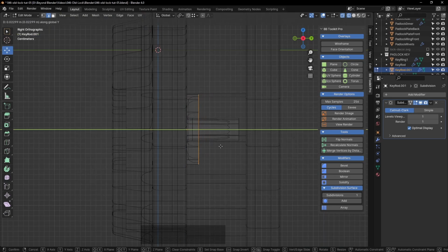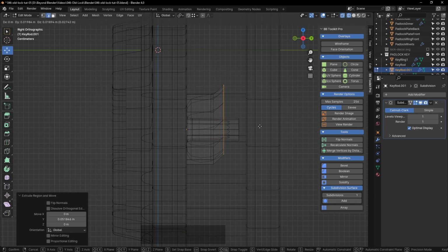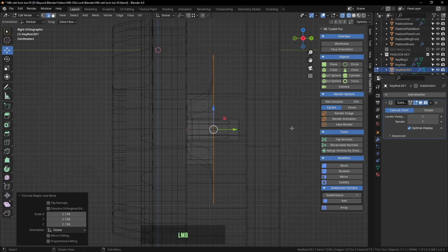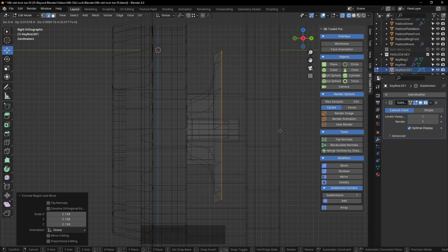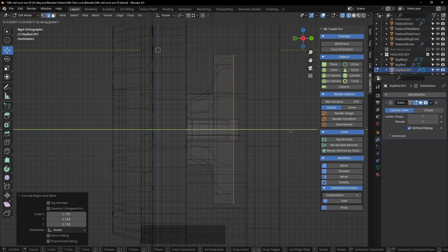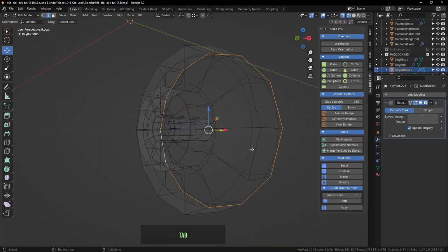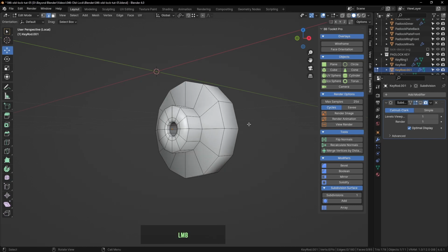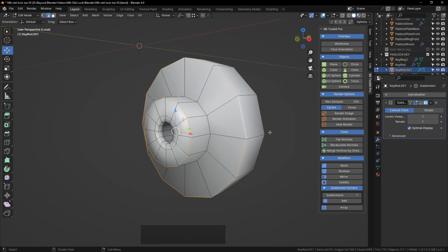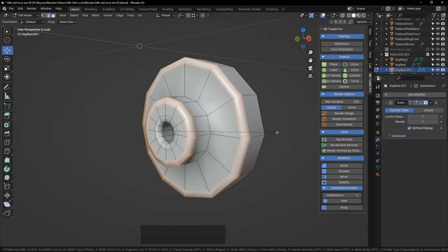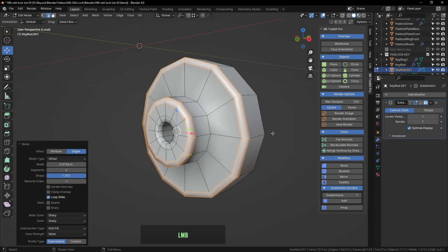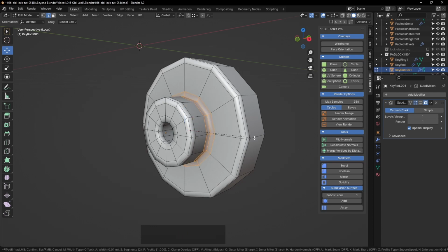So with that edge loop selected, I'm going to press E to extrude, and then the Y-axis left and right, and bring that in. And do that again, and then scale it out. So E and S. Something like that. And then E again, Y, and bring that back. And I'm going to use vertex snapping again by pressing the Control key to invoke snapping. So there we go. Basically, we have this tiny little shape like this. And we're going to select these edges there and add a bevel. And the inside, of course, we need to bevel that a little bit as well.